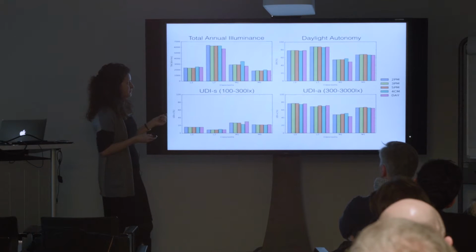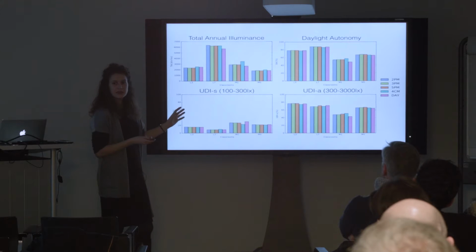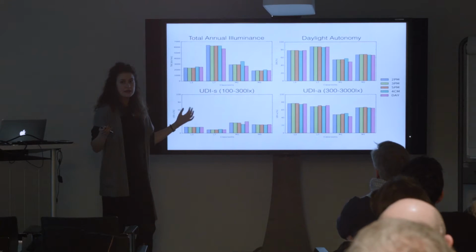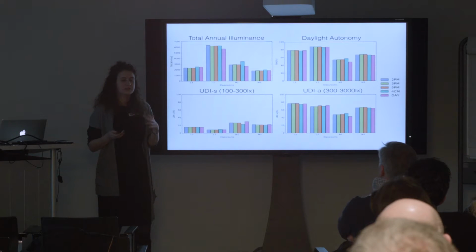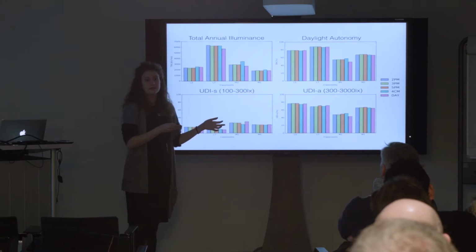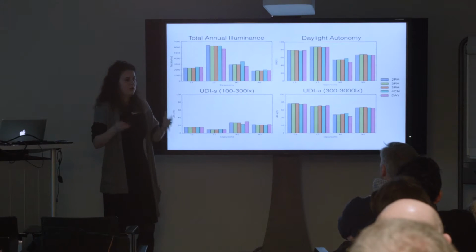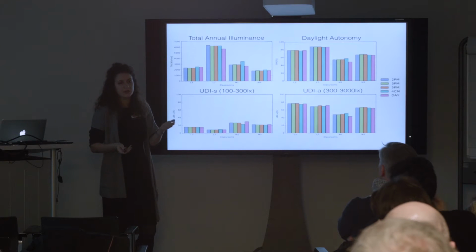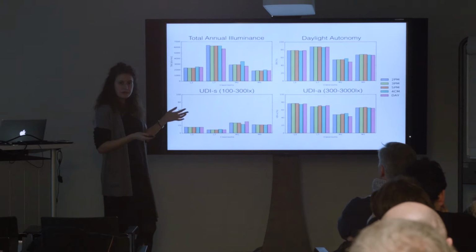Okay, so in general for CBDM metrics, no matter really which method you use, on an annual scale, the peaks would kind of disappear in the statistical binning that you make. So all the excess will enter in the UDI exceeded or in the daylight autonomy, and the result will be leveled off.